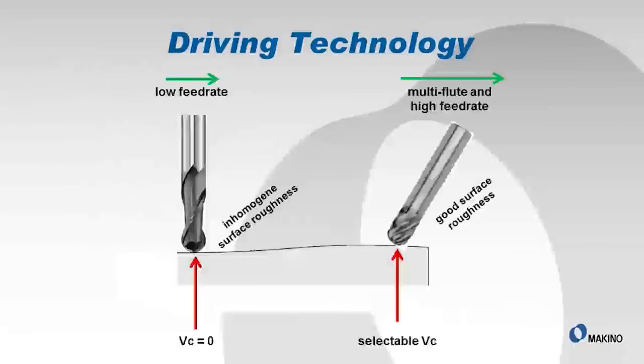One of the advantages of 5-axis continuous is also the ability to target the ideal contact point of the tool for the best cutting condition. As you can see on the picture on the left, you basically are trying to cut with the tip of the tool in this scenario, where there really isn't any velocity and it's more of a chiseling action, and you don't get good clean cutting of the tool. The picture on the right, where we've actually tipped the tool, we're maintaining it to a larger portion of the diameter and using a better portion of the tool to get good cutting conditions. With 5XC, you're able to maintain this good cutting condition by the control of the tool axis.